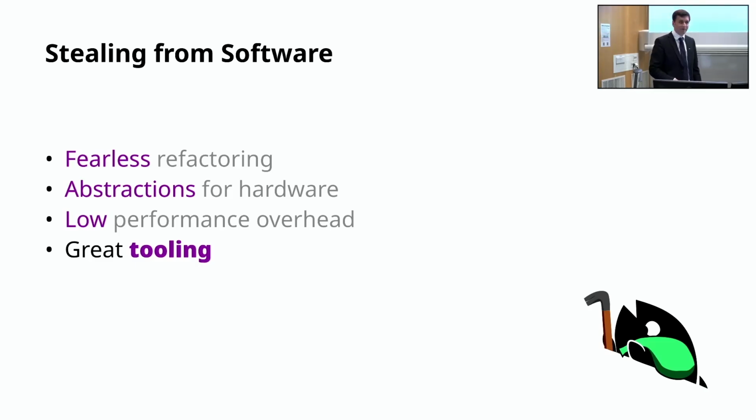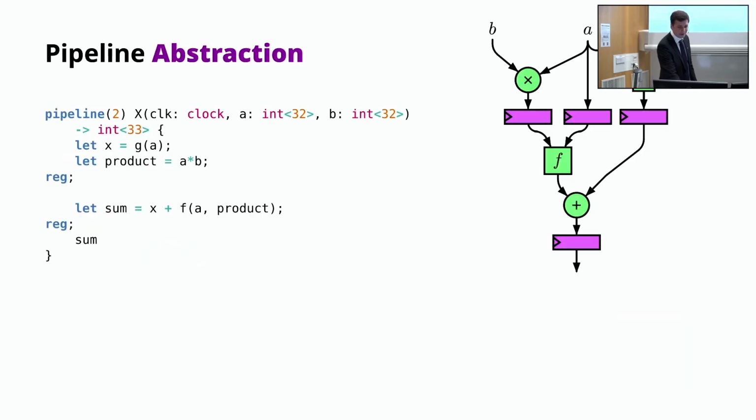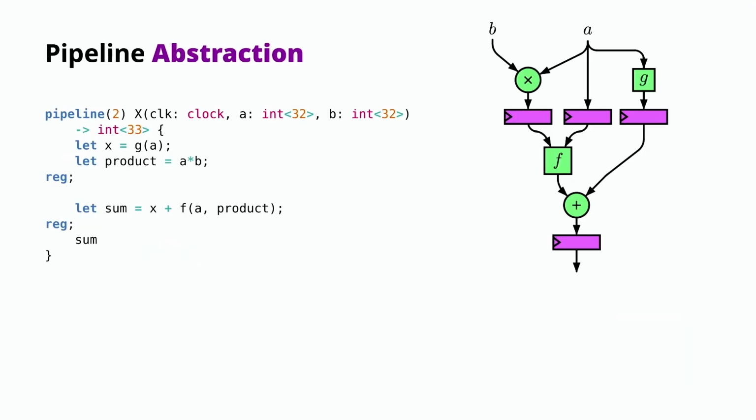So now I've talked about very abstract things for quite a while. Let's get concrete and talk about abstraction, namely the pipelining abstraction in Spade. This is one of the first things I did, and it sort of brings this idea of reframing a problem to highlight the important parts, namely the pipeline parts, and hide the unimportant parts, like exactly what is the name of every register in a pipeline. You can see I have some code on the left and some hardware on the right.